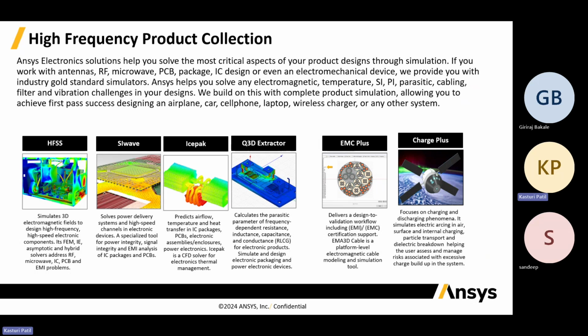Based upon the solvers, we can do these simulations. Suppose we want to design a simple antenna, we'll prefer the Ansys FEM solver. For antenna placement on a car, we need to select SBR+, shooting and bouncing rays. These are the kinds of solvers we need to select when we are designing antenna placement on some object.